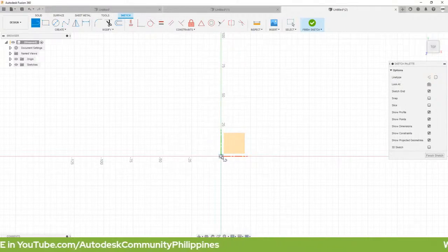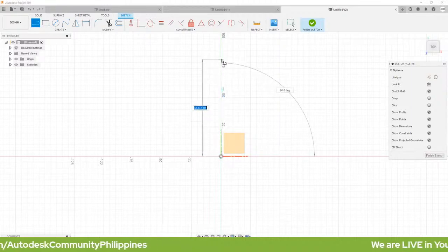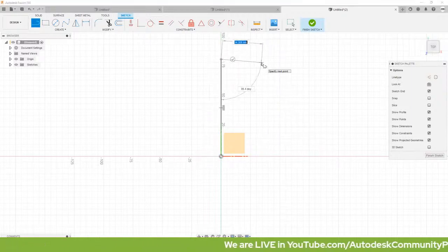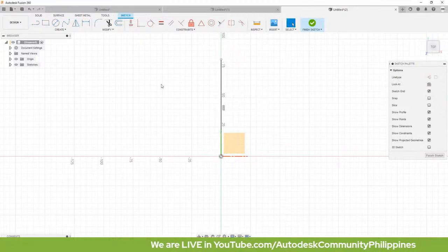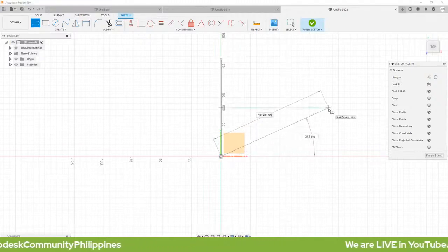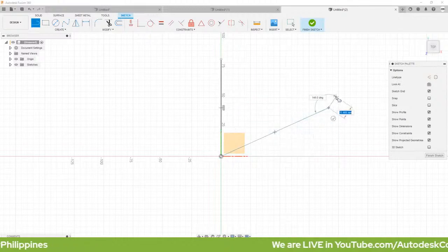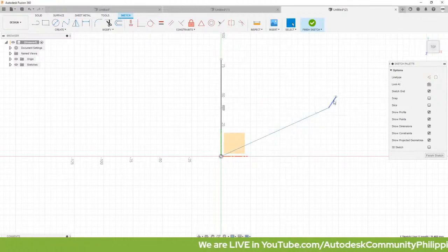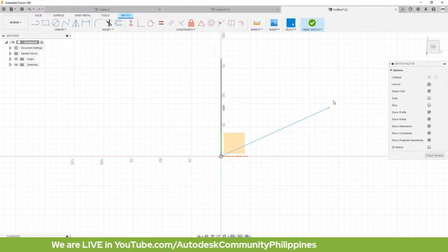Left click on our origin and make a vertical line. Left click, hitting escape, hitting L on my keyboard, left clicking on our origin, hovering over up, and left click, hitting escape, deleting this line. Now we're going to create circles.